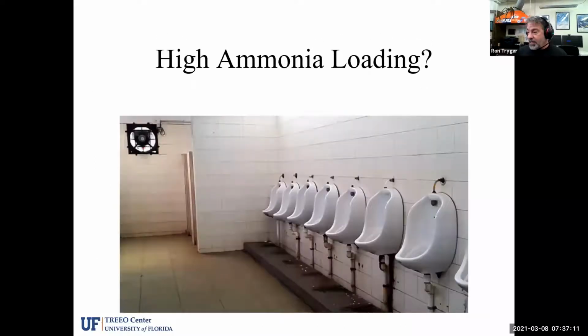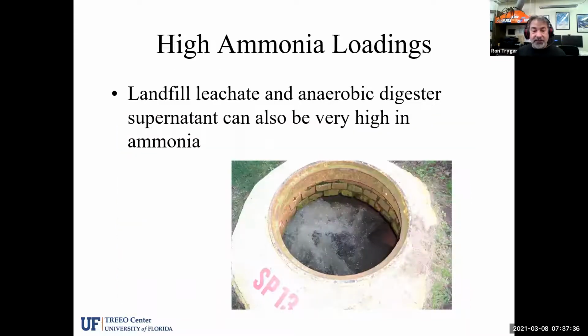So obviously we have a restroom here, a men's room, where we have a lot of urinals, and again, with low flow toilets, we may find that this load of ammonia and organic nitrogen entering the wastewater treatment plant can be very high during times when everybody's on a break or at halftime or whatever is going on at that event center.